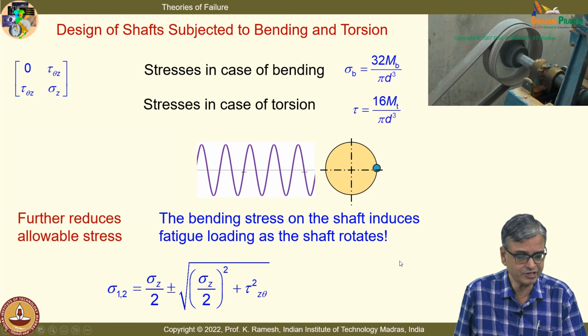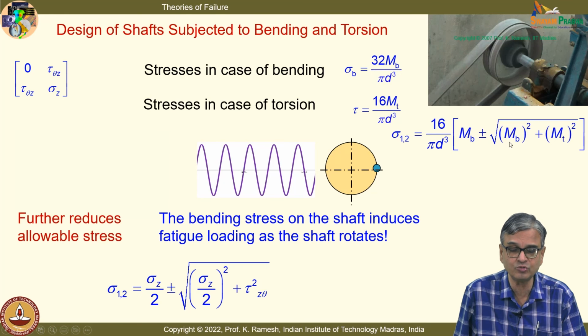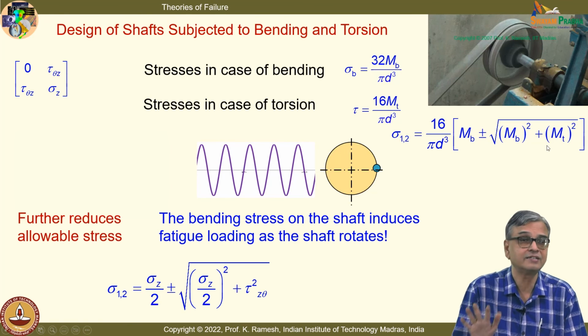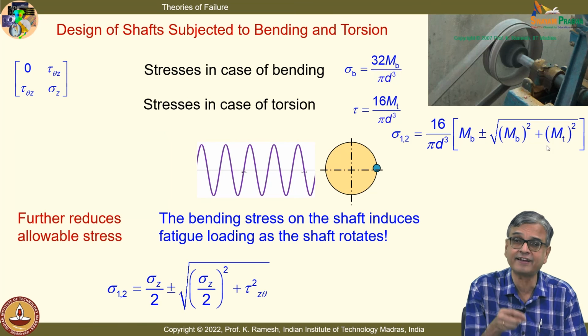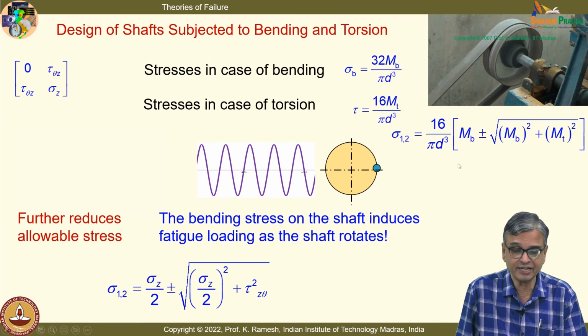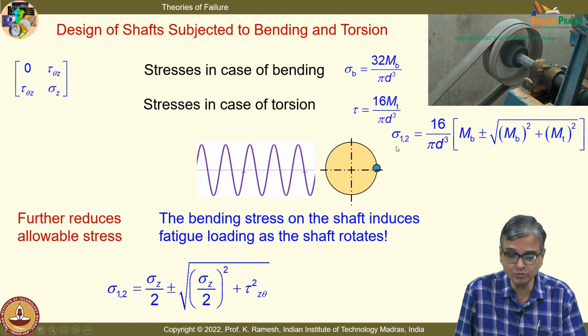So, when I have a shaft transmitting torsion and bending, you have a simple expression. They will estimate the diameter of the shaft just by using this. There is no torsional stress or bending stress in the expression, they are hidden. Okay. And you do not have to memorize this in your later course, you can derive it, and people use this in their design books like this. Okay.